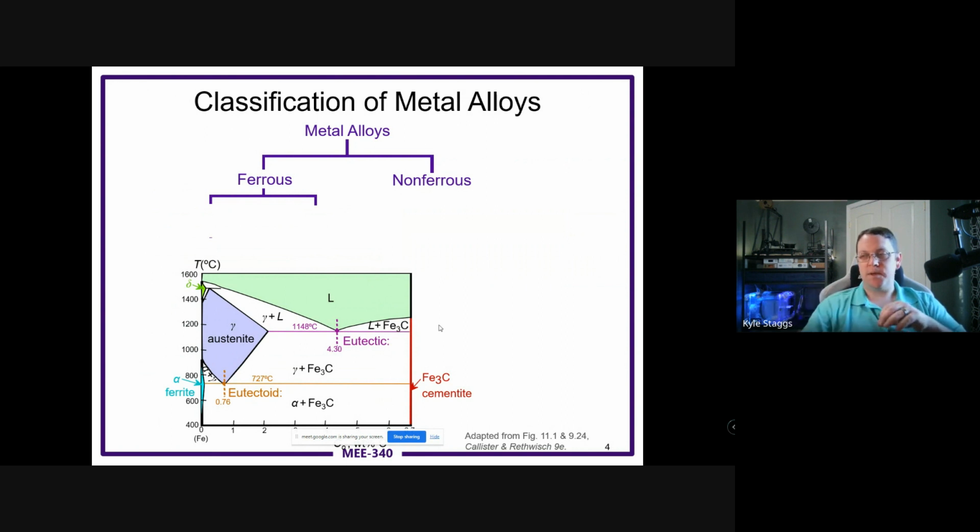So one of the old adages from welders is, if you can stick a magnet to it, you can weld it. That includes some of these cast irons, as you'll see in a second, as far as which region are cast irons. The downside is cast irons are much more fragile in a way. So they're very hard, but they're also very brittle materials. So you can weld the cast iron, but it's really tricky to do.